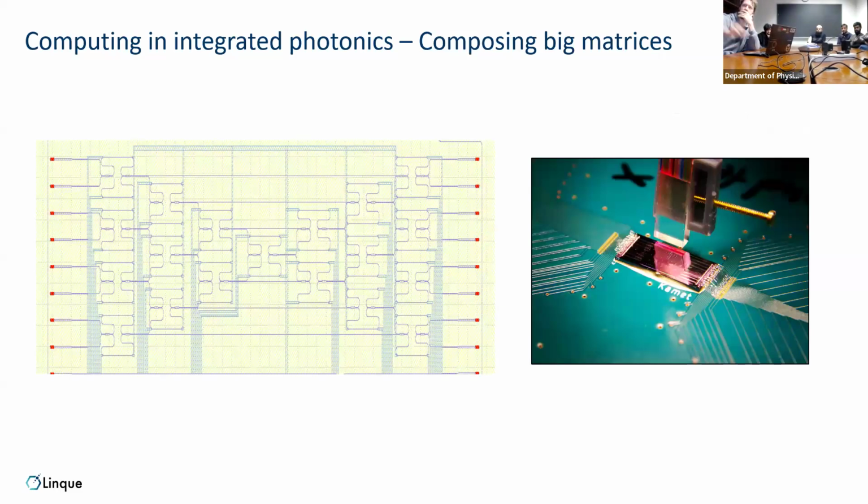But yes, this is a system that we actually built, like the picture you already saw in the beginning. This is the layout, which is actually what's used to fabricate the chip. You just have a network of these Mach-Zehnder interferometers, plug them together, and then you can make your computations. All these red dots are the input couplers, where you take a fiber array, which you see in the picture, just a bunch of optical fibers in a V-groove array, aligned next to each other. Then you couple them all in at the same time and all out at the same time and do computation.